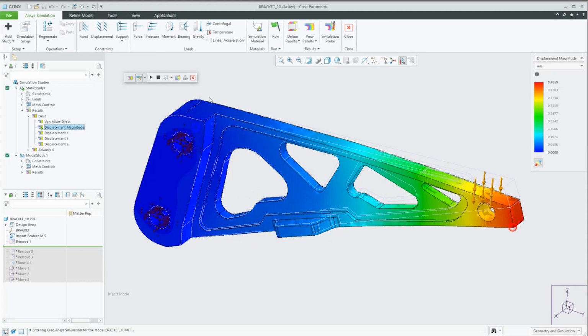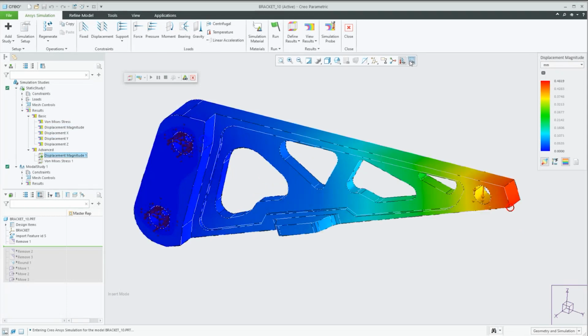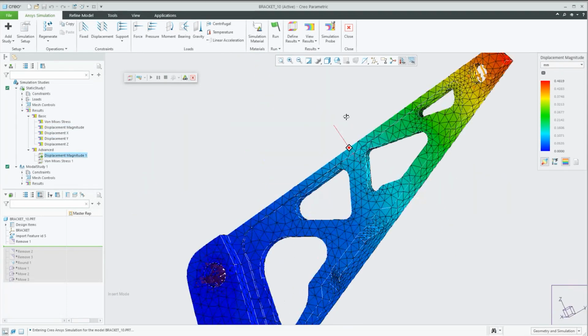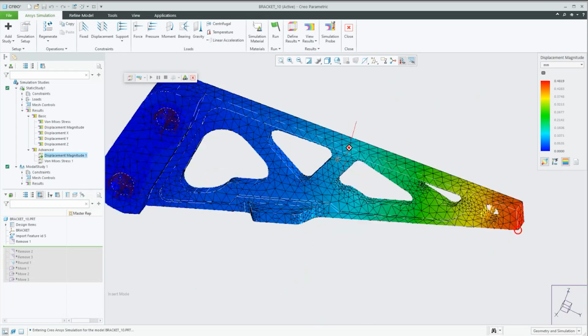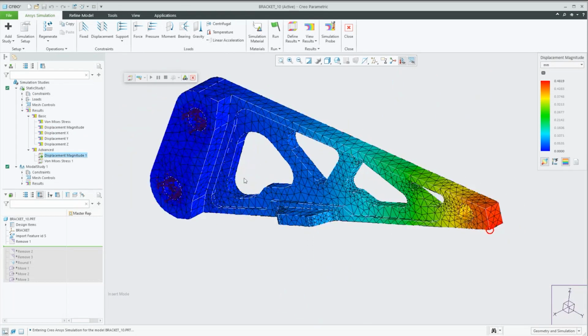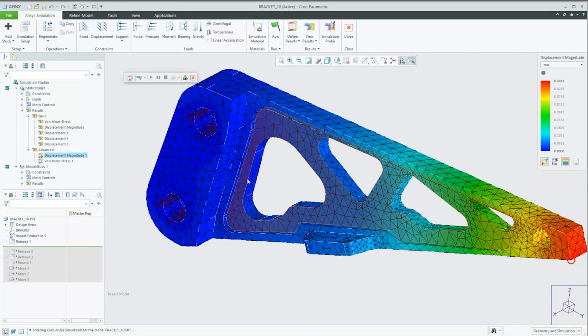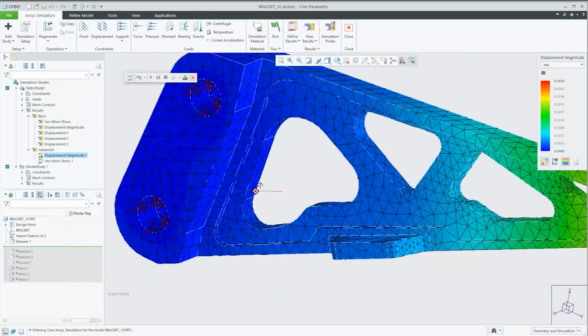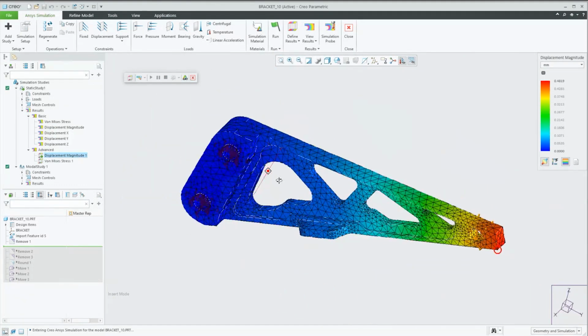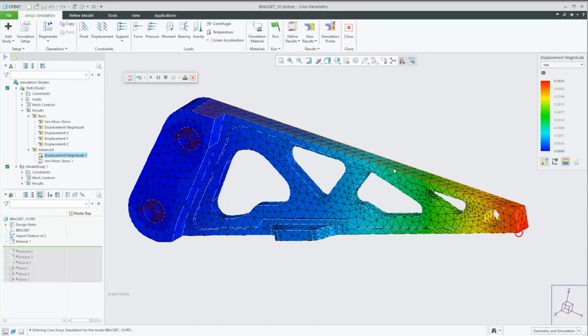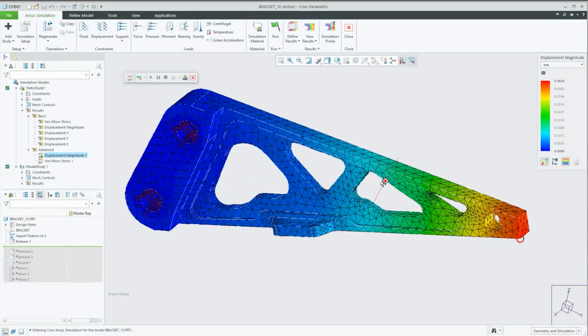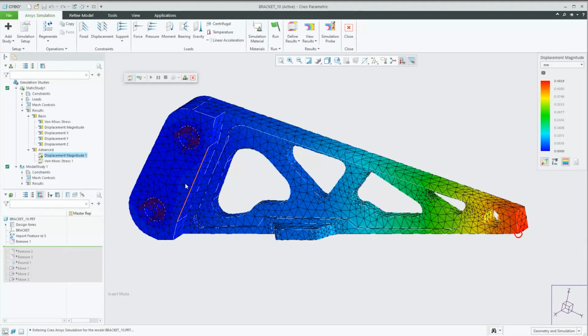If we've got these results, let me go into the more advanced version here. If we're interested to see what the finite element mesh looks like, this again is using automatic mesh generation, although I have changed a few of the default settings for this model, like the maximum element size. But it's handling the geometry pretty well.